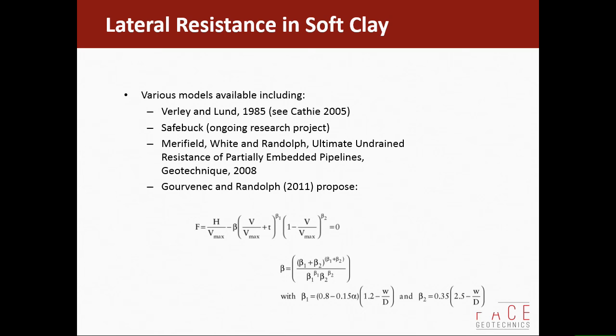The initial response is undrained. If you apply a load when the pipeline moves initially, that will be an undrained response. When it's laid, and then when it moves again for the first time, if it moves quickly, it's an undrained response.